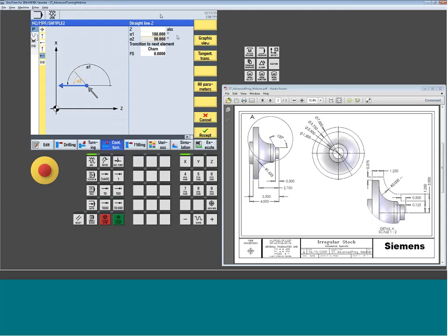And this triggers our trig help functionality. So whenever you don't know something, leave it blank, accept it, and then start drawing beyond. And if your numbers start to stack, things will start to automatically kind of fill in. So here, my next move is going to be an arc. So I do want to go into an arc event, tell it my direction, give it a radius, give it an end point.